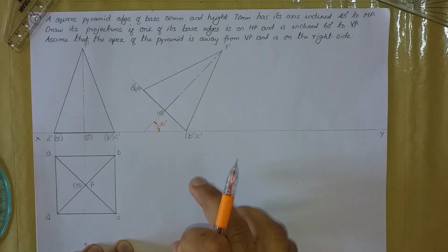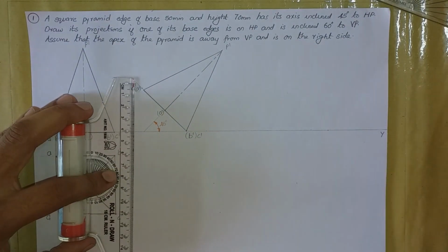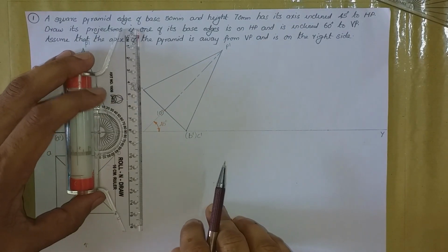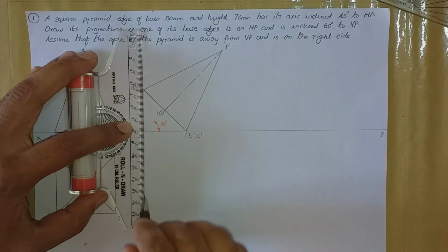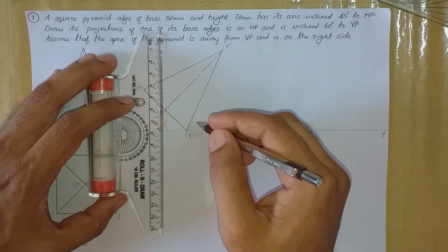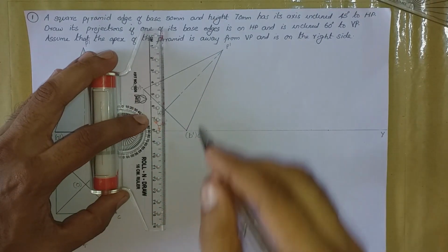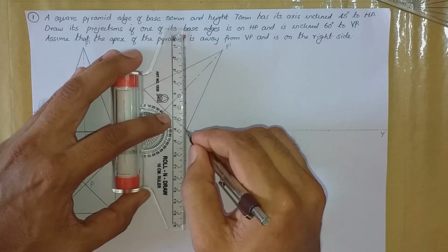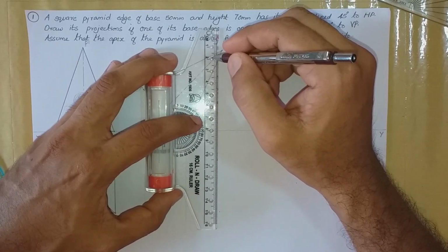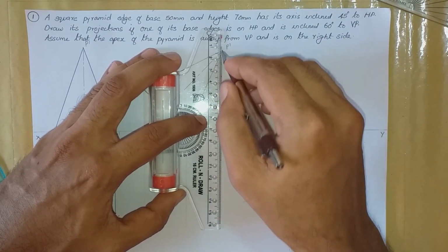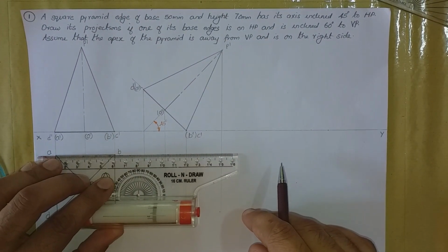Now we shall think about the top view. In order to draw the top view, we have to extend projectors from the front. So let us extend projectors from the front. From each and every corner of the front view, let us extend projectors. From the center of the base also we shall extend the projector. We shall extend the projectors from the previous top view.